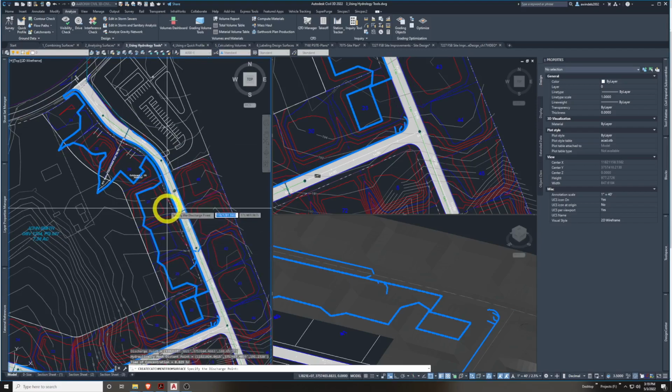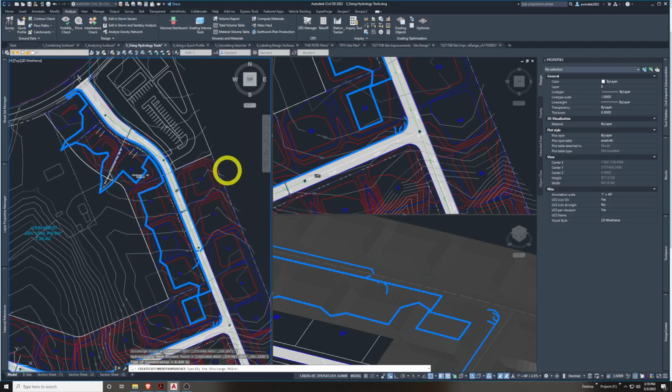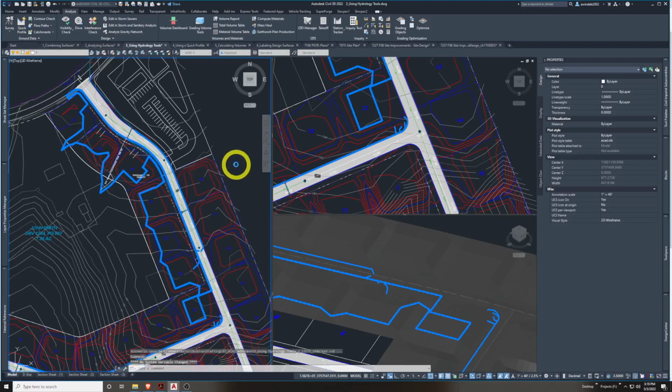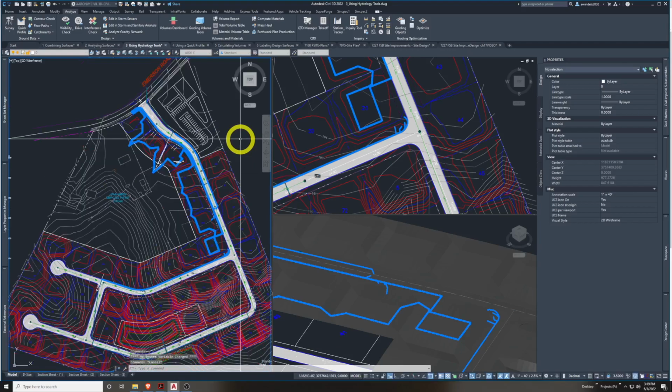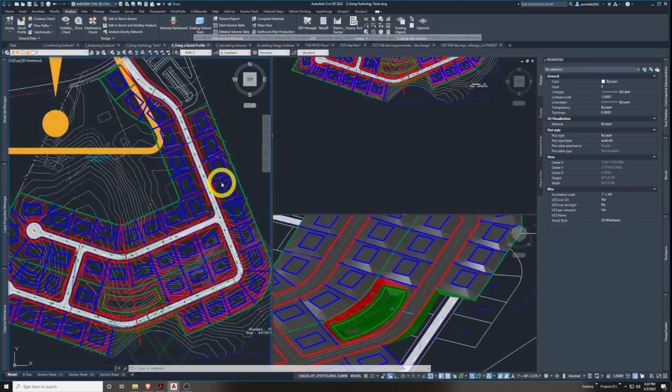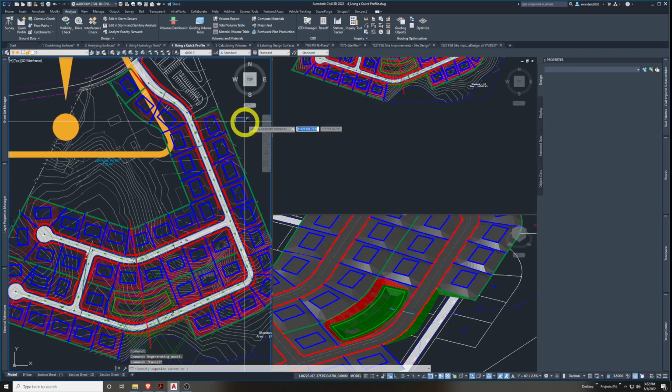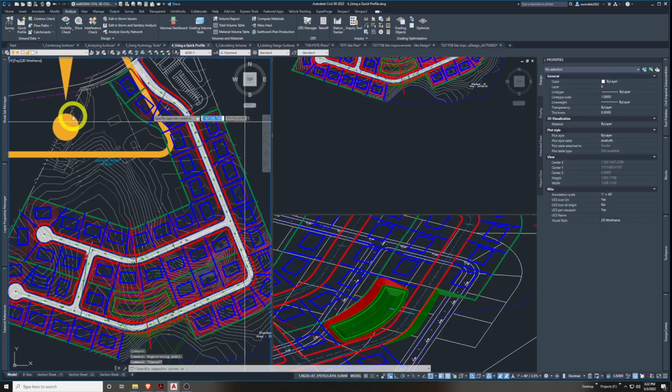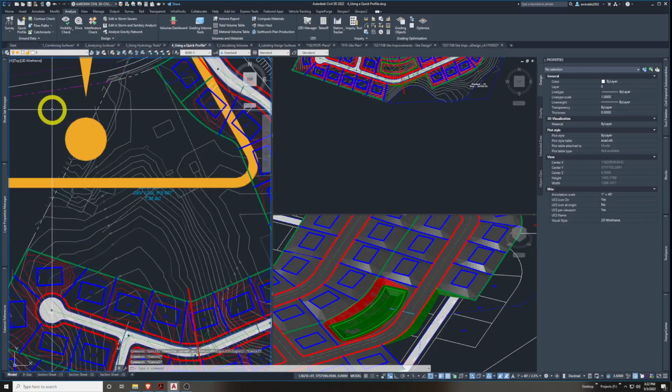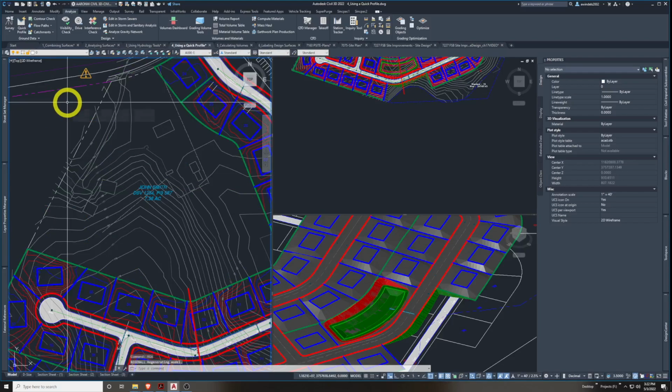So that's the end of 18.3. Let's move to 18.4, learn a little bit about quick profiles, how we can use them for fast analysis to analyze our 3D design. So jumping into the fourth file, using a quick profile, if you see a big warning symbol like that, just hit the regen all or start typing in regen all to make it smaller. If it's getting on your nerves especially, which they can.